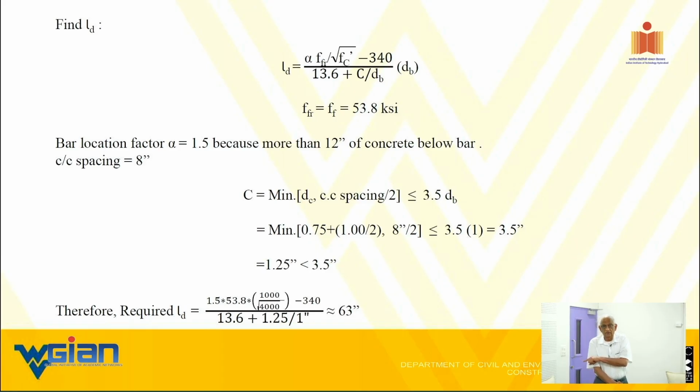I need to qualify. What this 36 they're talking about is with respect to steel, and with respect to composite, it's almost 60 times. That does make sense, implying that when we run the tension test, we find you get a better value with a larger gauge length as opposed to a shorter gauge length in tension.